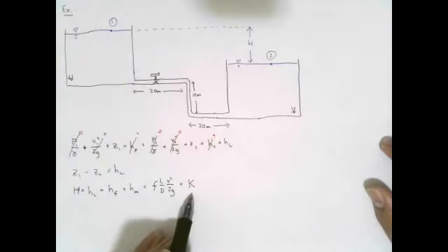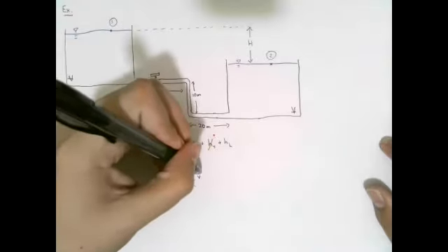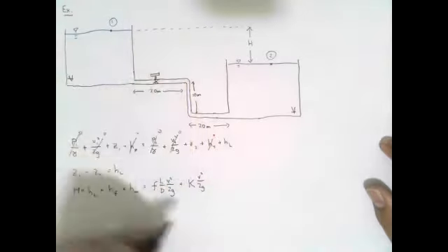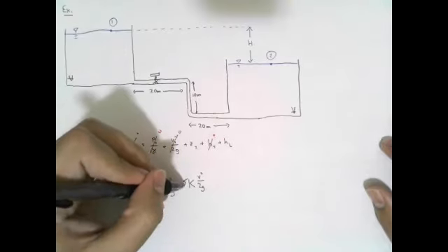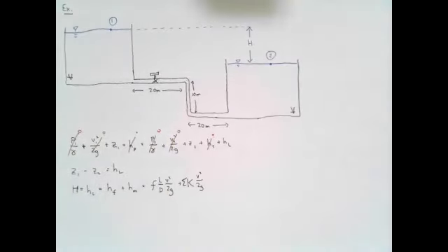Now, this minor loss coefficient corresponds to only one element, one component in your system. But if you have multiple components in your system, all you have to do is add up all of those multiple coefficients. So it's not really that big of a difference. You just add all of your coefficients up, okay? So let's see if within the next 5 to 10 minutes, we can actually try to solve this problem.